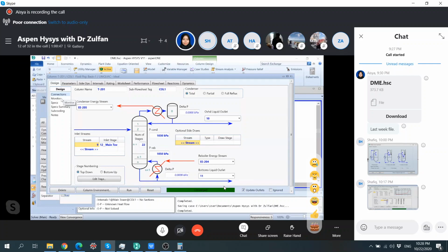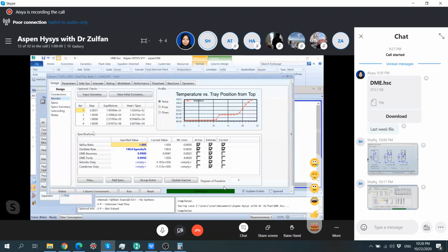But what are we trying to look at in the pattern of the reboiler duty and condenser duty? Basically, if you are to run these columns, the reboiler, for example, will be using steam, like a hot medium. So this steam or hot oil or whatever comes with a price, so we have to pay for it. The same goes with the condenser, even though it's much cheaper because it's going to be cooled with cooling water anyway.